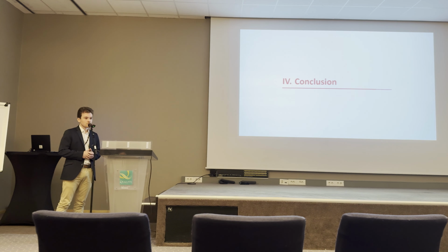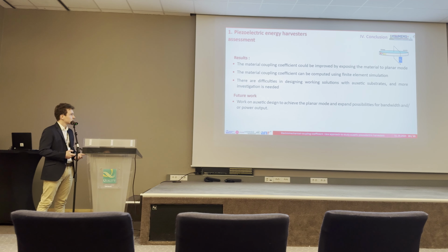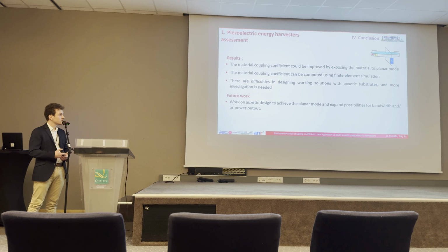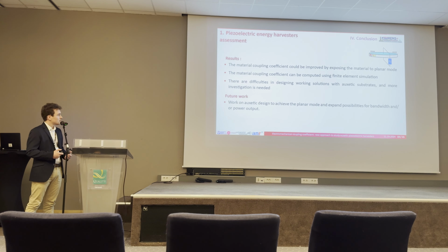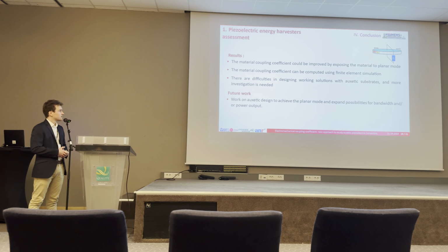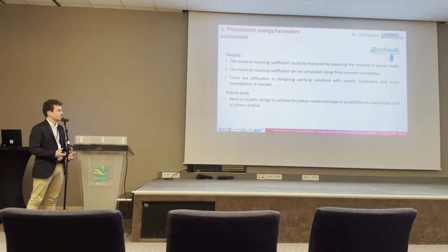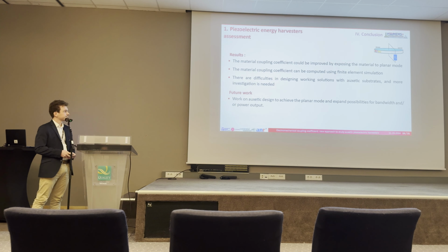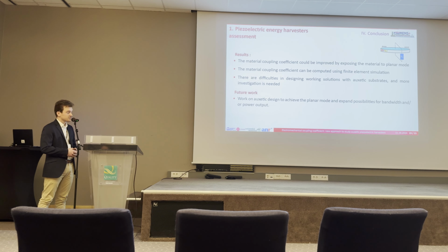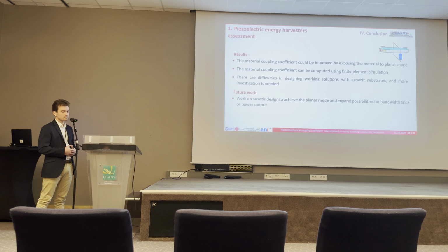So let's get to some conclusion. As a result, we saw that the material coupling coefficient can be improved by exposing the material to planar mode. The material coupling coefficient can be computed using finite element simulation, but there are still difficulties in designing working solutions with auxetic substrates, and more investigation is needed. The further work here will be to work on auxetic design to achieve the planar mode and expand possibilities for bandwidth and or power output.